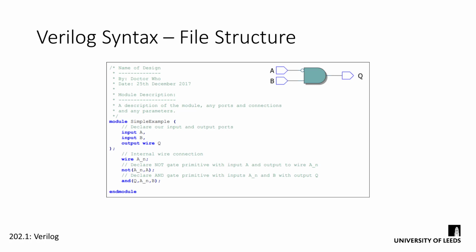One thing that's very important when it comes to FPGA development, and something that you're going to have to work hard to remember, particularly when we do sequential logic later in the semester, is that all HDL is executed in parallel. You're describing a circuit here, not a step-by-step list of instructions. It can be very easy to forget this when you're writing behavioural code further down the line, and that can result in significant errors in your circuit.